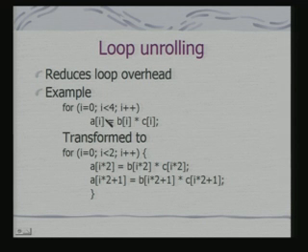So effectively I can do the same computation using fewer loop iterations, and the loop overhead goes down. Now you can say that I have introduced these multiplications, but if you remember, say, the ARM architecture, these are not really multiplications. They can be done as part of the same instruction itself because of the barrel shifter. So I get much better optimized code for the loop.